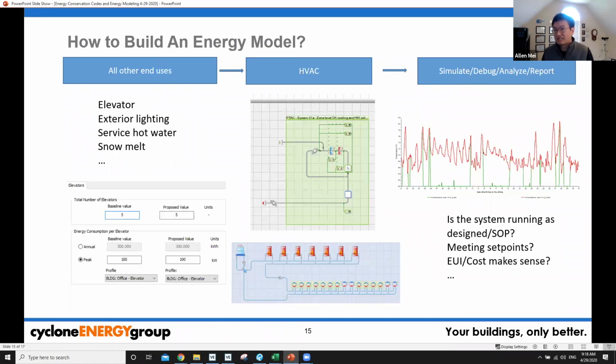And the next step is, there are lots of things happening in a building, right? If it's a high-rise building, let's say a 40-story building, you're going to have lots of elevators, and huge elevators. You're probably looking at around 200 kW per elevator. Oftentimes they have different types of elevators, traction, regenerative, just different drives. And those elevators actually consume a lot of electricity, a lot of energy. So you have to count them.